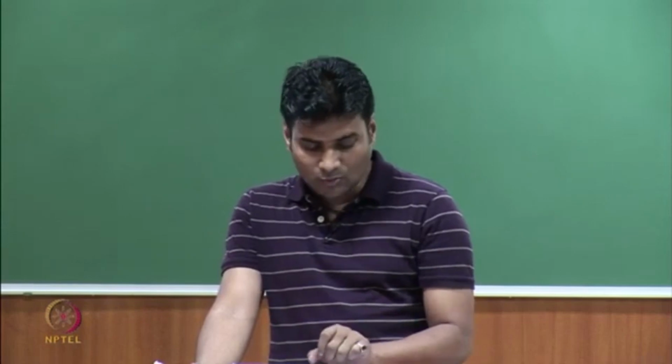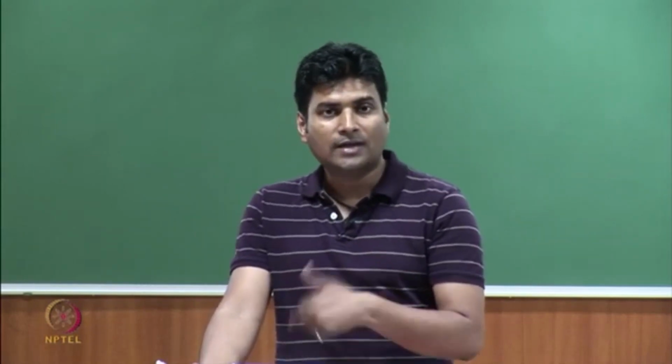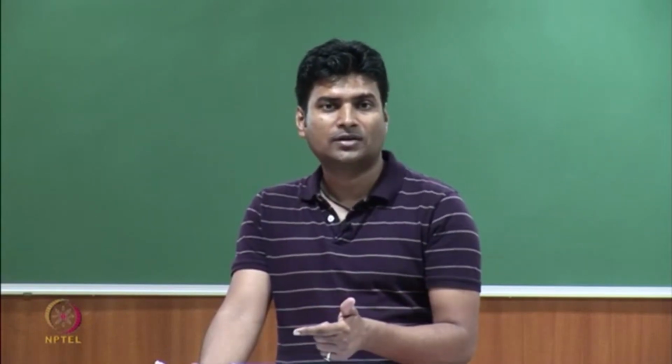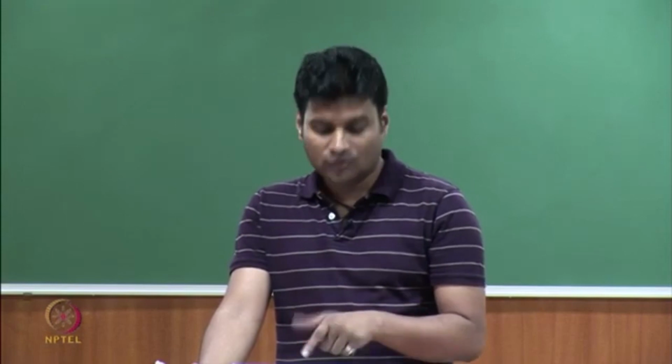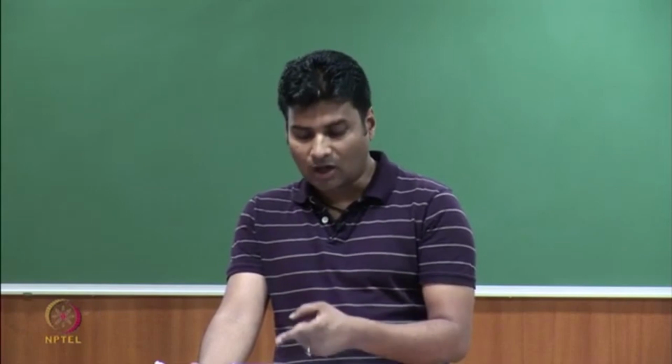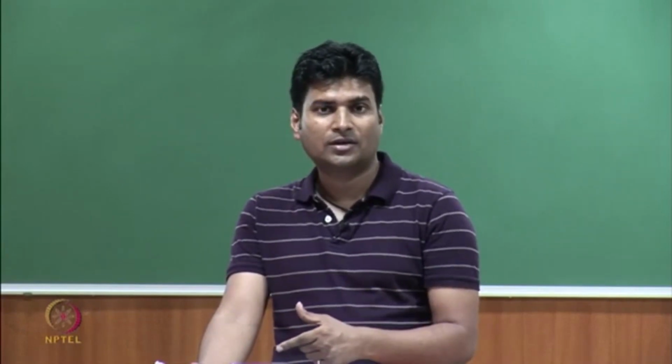Now, when you add these two, you have sigma z z and minus sigma z z. So, they cancel out, and the derivative term is with delta z by 2 and it is the same. So, delta z by 2 into 2, it becomes delta z, right. So, can you see that only the derivative term survives here? That is going to happen when you do Taylor's expansion of tau theta z as well as of tau r z, right.